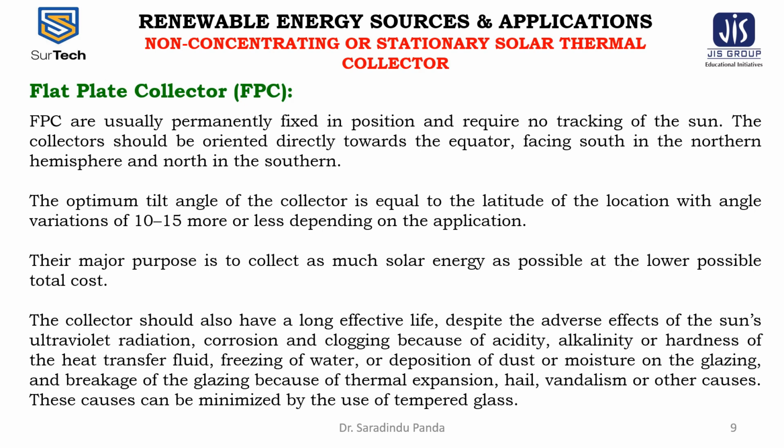The collector should also have a long effective life despite the adverse effects of the sun's ultraviolet radiation, corrosion and clogging because of the acidity, alkalinity and hardness of the heat transfer liquid, freezing of water, or the deposition of dust or moisture on the glazing, and the breakage of the glazing because of thermal expansion, vandalism, or other causes. These causes can be minimized by the use of tempered glass.